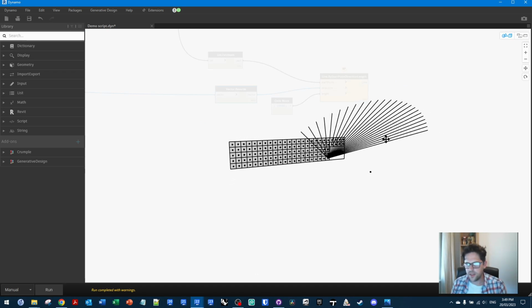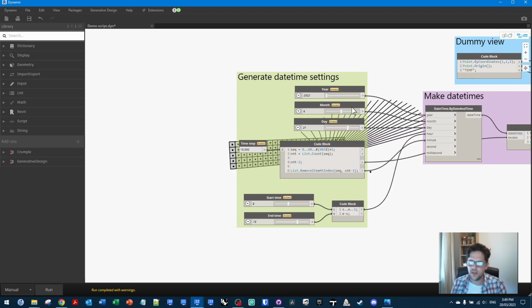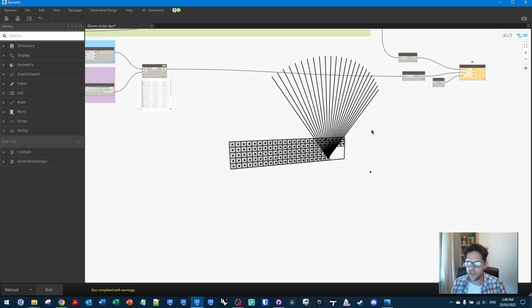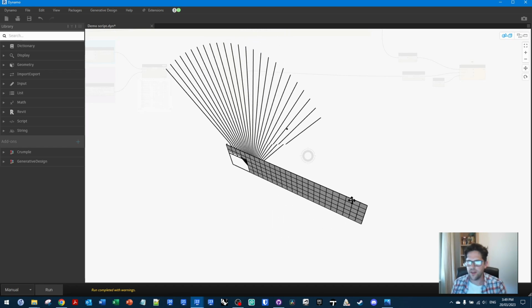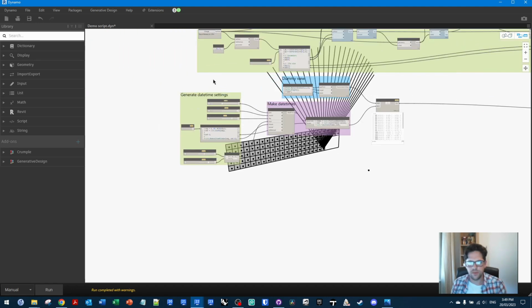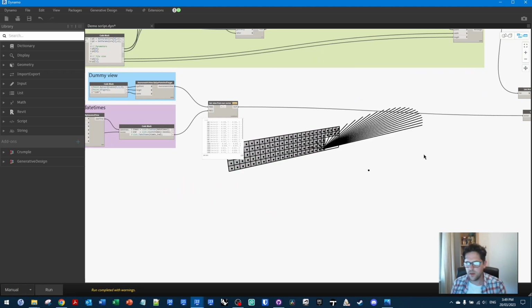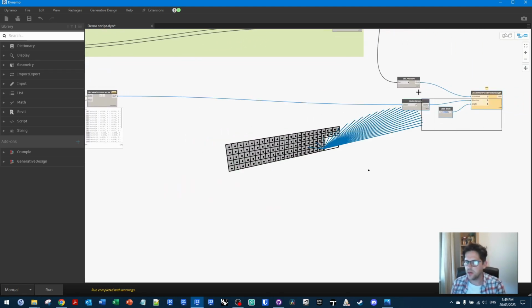And let's do a test. Let's change the time of year to when the sun should be higher. In this case, in December. And just make sure that that works. And there we go. We can see that makes a lot more sense. So I'm pretty confident this seems to be working and generating a sun path that is definitely coming from Revit. So I'm just going to go back to June and keep those angles for now. So I'm pretty happy with this.